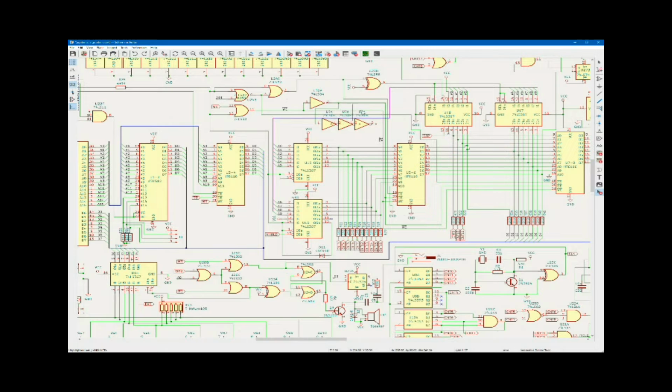Now what we will do is get rid of the old write enable wire. That's that one. I will come in here and take this. Let me just clean this out as well. So now, instead of the write enable coming off of there, we've got this write enable delayed approximately 80 nanoseconds later. And by my thinking, that will make sure that these address bits are set about 20 nanoseconds before the write pulse hits the RAM over here.